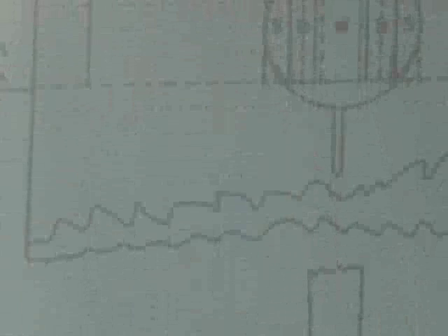The idea is to do it in a way that people can use your data. If you go to the lab and crack a sample without keeping track of how big the crack is as opposed to the width of the sample and all that information, it may be okay if you're doing the same geometry, same loading as you have for your project or your service condition. When it comes to making a more generalized analysis that you can use for different locations, let's say you're going to run FEA or do something like that, a lot of times you end up having to run a standard